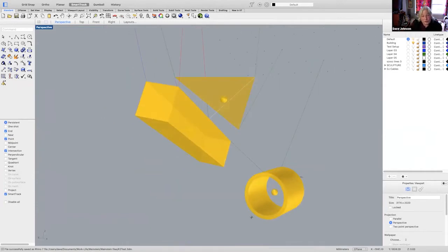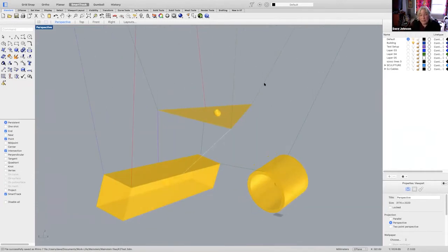One of the cool things it does is it looks at the tensions in the cables and colors them accordingly. So if the cables are tense, then it colors them between green for least tense to red, most tense. And if it's a kind of a slack cable, then it colors it magenta or lavender through white. So I don't know if you can see this, but this white one, that's a pretty slack cable for sure in this arrangement.